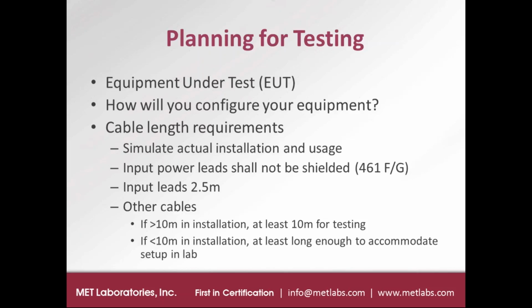During planning for testing, you want to consider certain specific details about the equipment under test. You want to think about how you will actually configure your equipment during EMC testing. A lot of times, the way the equipment is configured in the installation isn't going to work exactly for EMC testing. Also, MIL-STD-461 doesn't necessarily allow for the actual installation conditions. They do want you to simulate actual installation conditions.